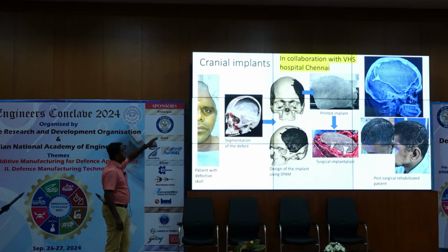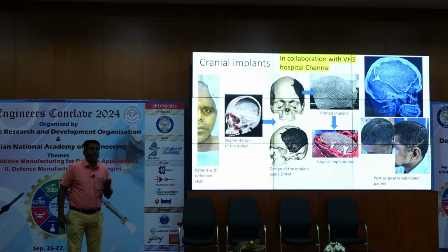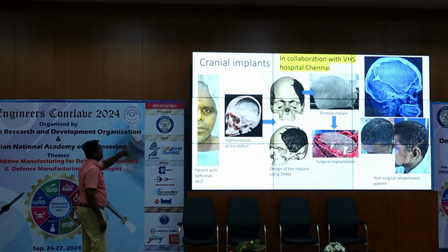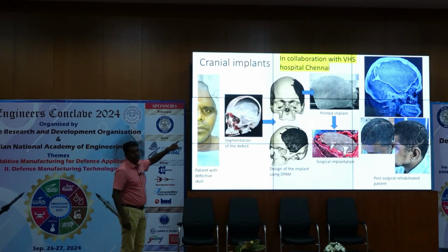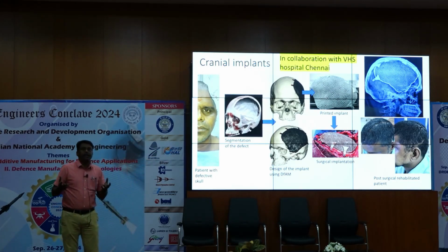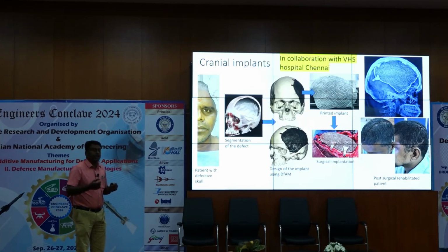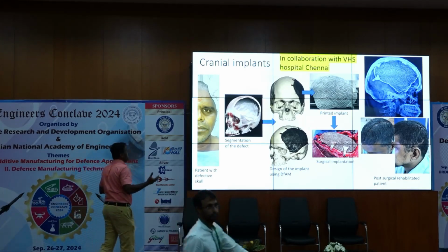And the advantage here is with 3D printing, we can also use the design for lightweighting. Like what you see here in the implant, this is a titanium Ti-6Al-4V lattice structure. By introducing that, we also introduce an offsetting property and lightweighting. If you make the same implant with solid titanium, it will weigh about 152 grams. But with the lattice structures, this implant weighed about 40 to 42 grams. So this is as light as the human skull.